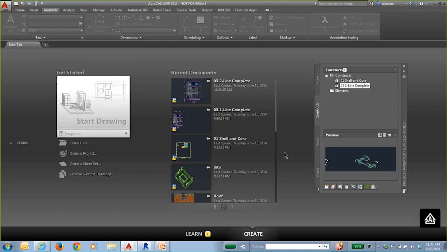A couple of other things as far as the visual indicators. A red check mark will denote that the file is checked out by other users. So if I had another user using one of these files, it would be a red check mark, not a green check mark, which is what shows what I have checked out. And every time a file is checked in or out, a record on the version history identifies the user who performed the checkout. So if we were looking here, you can see that it was modified by me. And I can see that on the check-in and check-out history of the Project Navigator. So that might come in handy as far as dealing with files over time.